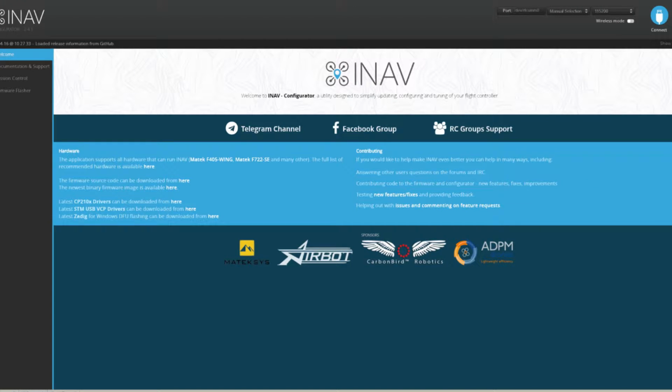Today we'll be focusing on flashing the INAV firmware on our flight controller and making sure it works. To get started, you will want to go to the description and click on the link below. That will take you to the INAV configurator download page. The most current one for me is 2.4.1, but I'm sure the same process will work in the future.